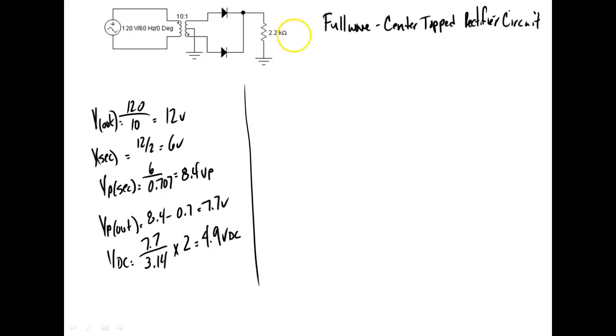Current in the load, right? So I of the load would be equal to 4.9 divided by 2.2K. Where'd y'all learn this at? DC, right? What would they give us? 2.25 or 2.3. Either one of both, okay. And this is milliamps, so that's K. Usually when you divide whole units by K, you usually get milliamps. Unless it's 100K, then you usually get microamps.